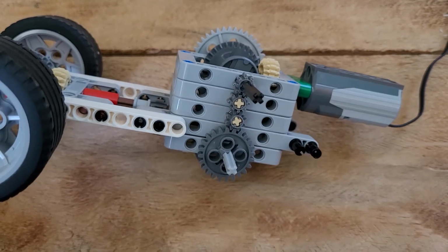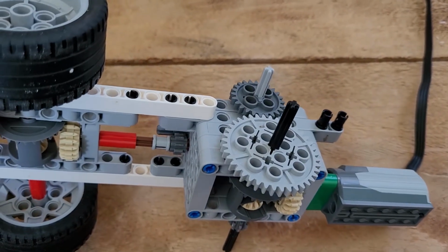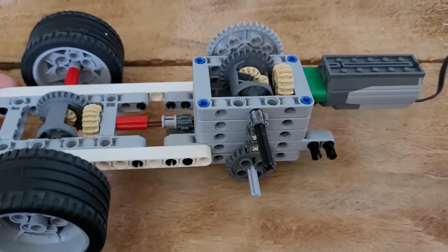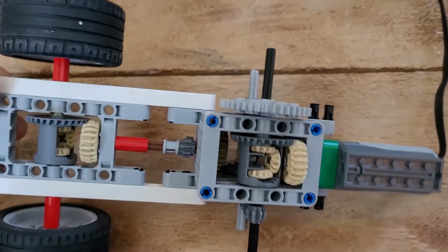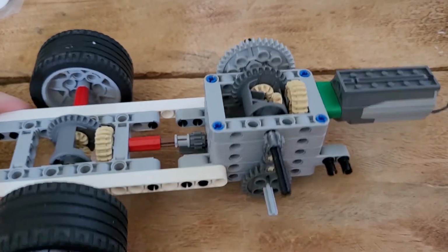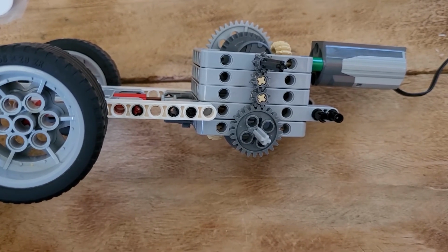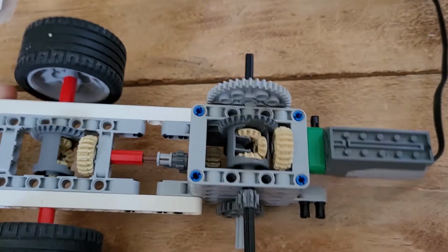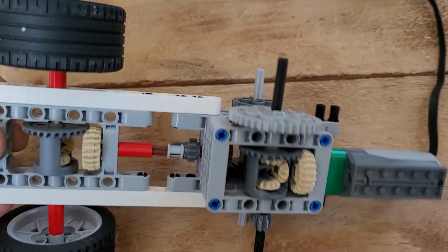The reason for that is we needed 4 gears on this side, as we have 2 gears on this side, so that we can be turning in the same direction, but also having 2 different gear ratios. Now, on the opposing side here, we have a large gear driving a smaller gear for our overdrive, and obviously with a small gear on a larger gear on this side, this is going to be a lower gear. So the way I have this set up is that this is first gear, equilibrium between the two is second gear, and then our third gear in overdrive is this side.